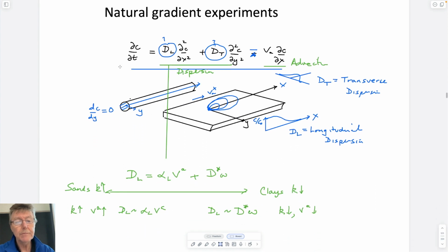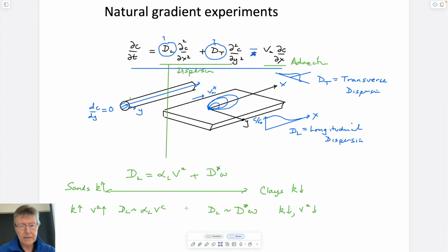So we've talked about the mechanisms by which fluids get advected down gradient and spread out. We've rationalized it in terms of an equation where accumulation is equal to the advective transport that physically moves the front downstream, and also the dispersive transport, which spreads the front out as it moves downstream, both longitudinally, and also in the 2 or 3 dimensional case, transversely to spread out the plume.